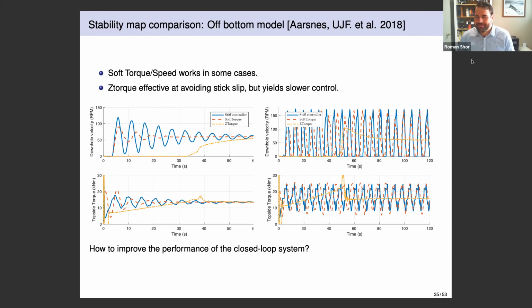Eric. Yeah, I have a question for Jean. You mentioned in your controller that you are using a maximum torque or torque limiter for when you have some high torque demand. Do you have a torque limiter which depends on the rotational velocity? Because in a normal top drive, you will have a flat maximum torque when you are in current limiter mode of the VFD drive, and then it will be a kind of hyperbolic response above this because of the increased impedance at larger frequencies. Yeah, no, we just use the constant one.